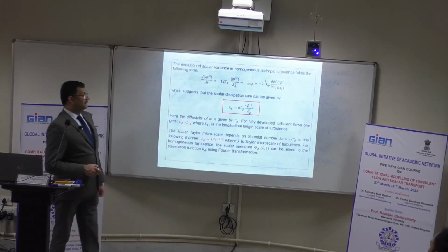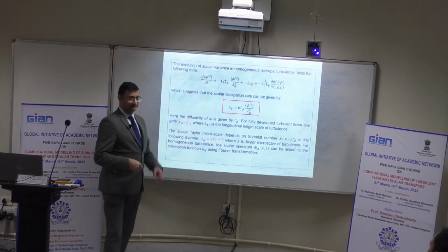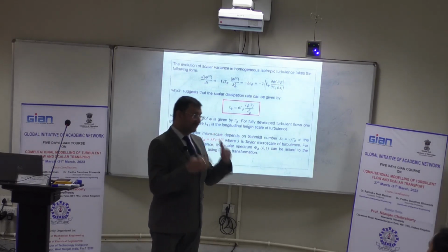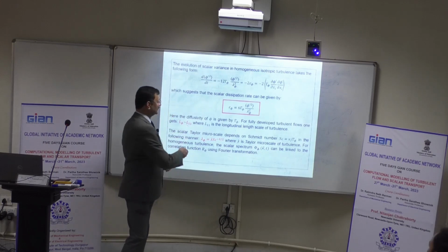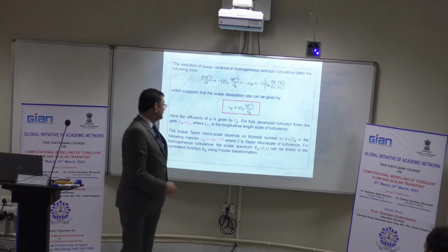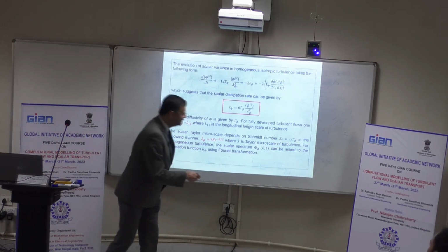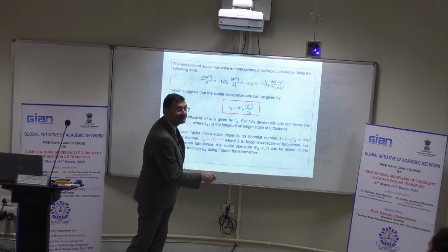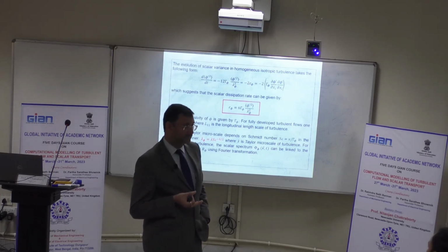For fully developed turbulent flow, one generally gets L phi, that means integral length scale of scalar, approaches this, which is the longitudinal length scale of turbulence. The Taylor microscale depends on the Schmidt number, which is a material property given by the kinematic viscosity to molecular diffusivity ratio.